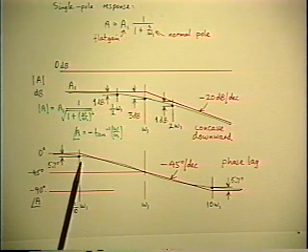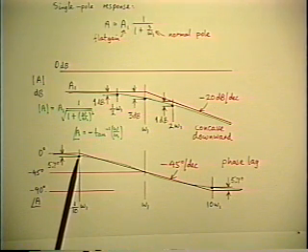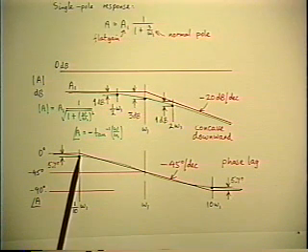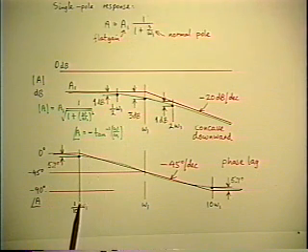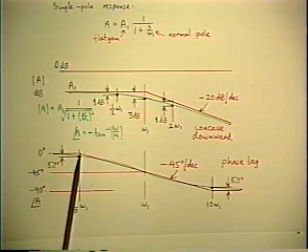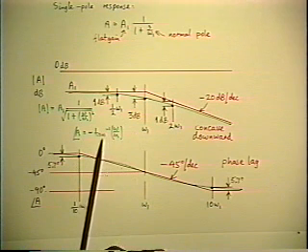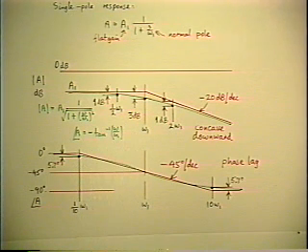The maximum deviation actually occurs at the asymptote intersection. And it's easy to evaluate that, because if you put in the formula omega equals 0.1 omega 1, which is where that asymptote intersection is, arctangent of 0.1, remember some high school trigonometry? Series expansion of the arctangent function. You probably don't remember it.